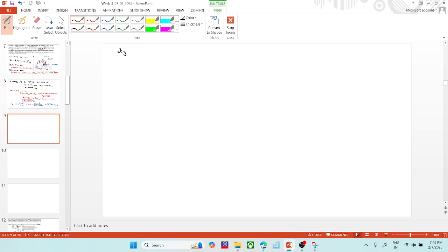While we equate S3 is equal to S4, the expression would be 7.759 is equal to SF at 0.008 plus X4 into SFG at 0.008. We are having all these values, so when we put the values, we will get the value of X4 as